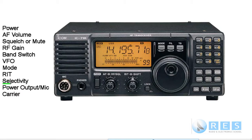Selectivity. Selectivity is the ability of a receiver to reject unwanted signals and just receive the wanted signal. To be able to make a receiver more selective, radio amateurs generally have to have filters installed in the receiver. So if you're a real keen Morse code operator, a CW operator, you would have a crystal CW filter fitted to your radio. You have an SSB filter, 3 kilohertz wide, already fitted to your radio, and some radios have multiple filters for different modes fitted to them.